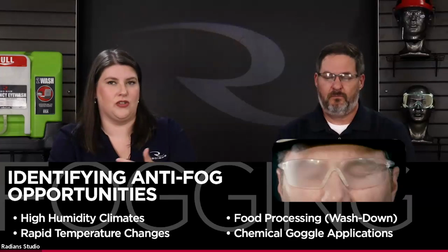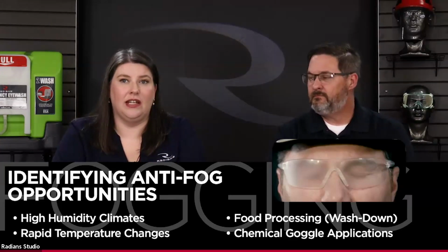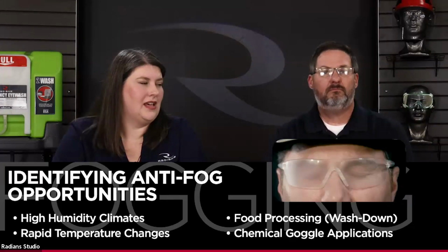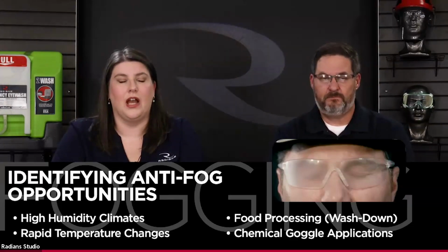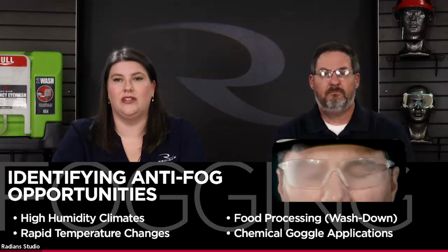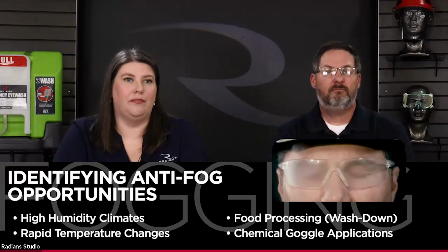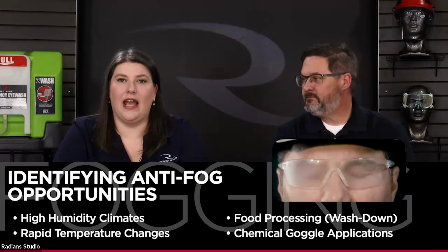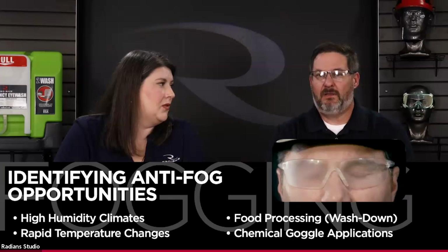Those temperature swings are going to create fogging opportunities. Food processing facilities and wash down areas, even a chemical parts washing station, have high potential for fogging due to the temperature of the water. You've got chemicals in play. Anti-fog is important to have on any goggle being used in chemical environments.